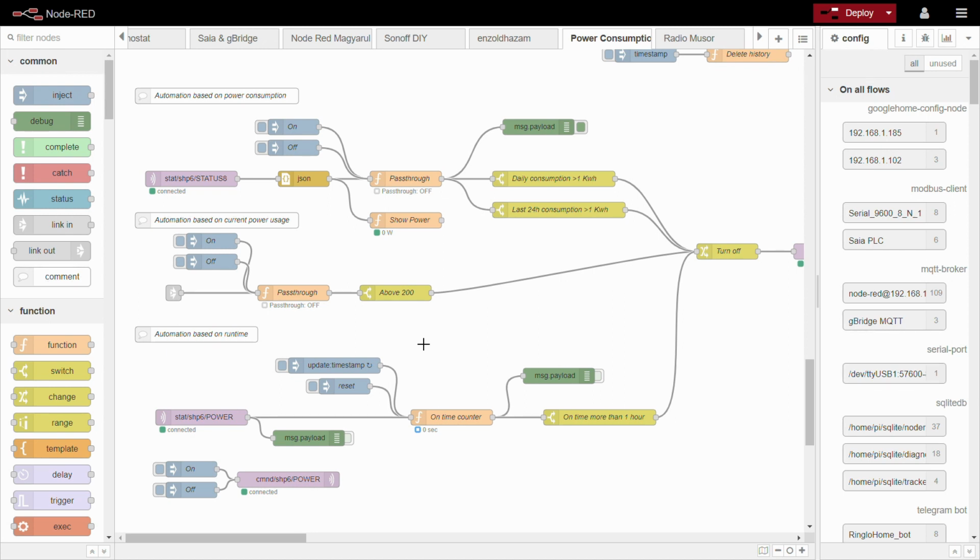And of course, there's a float switch at the top, but what happens if the float switch gets stuck? Then your pump is running all the time, and probably your tank or whatever is overfilling. So I think it would be a good idea in some cases that you look at when your device gets turned on and then monitor how long it is running continuously, and if it's running for a certain amount of time, then you just kill it. And this is what I've implemented here.